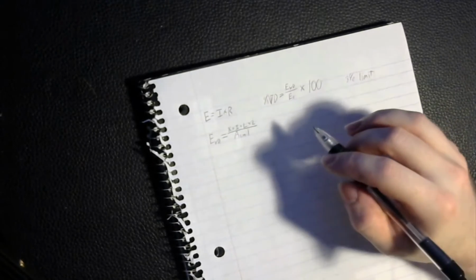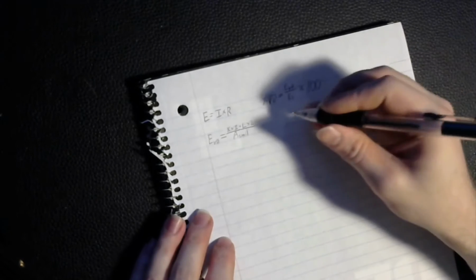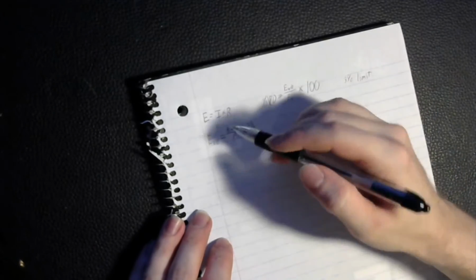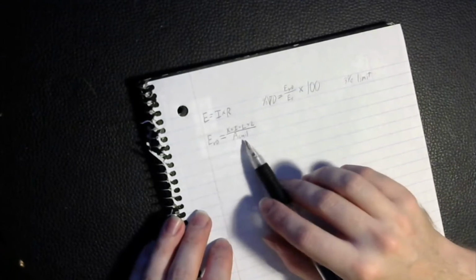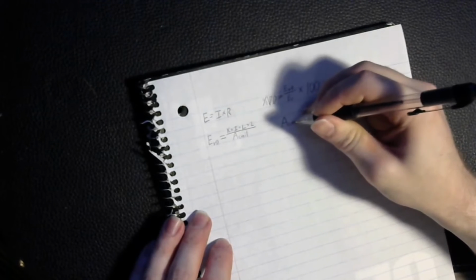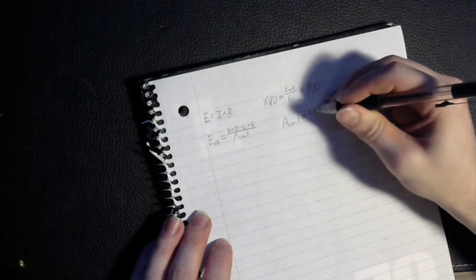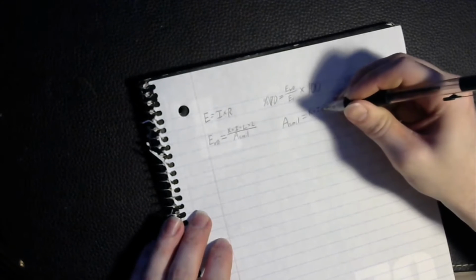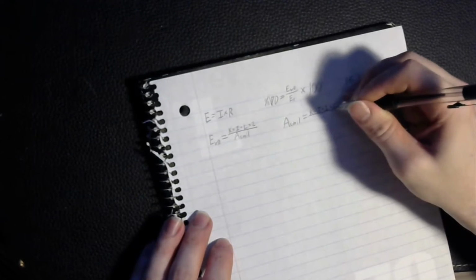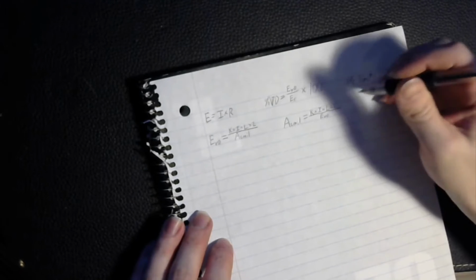There's at least one problem on the homework assignment where you'll have to use this, and if you specifically just need to get the gauge of your wire, you can literally just flip your voltage drop and your area in circular mils around. So the area in circular mils would be equal to your constant K times your amperage times your length in feet times 2 divided by your voltage drop.